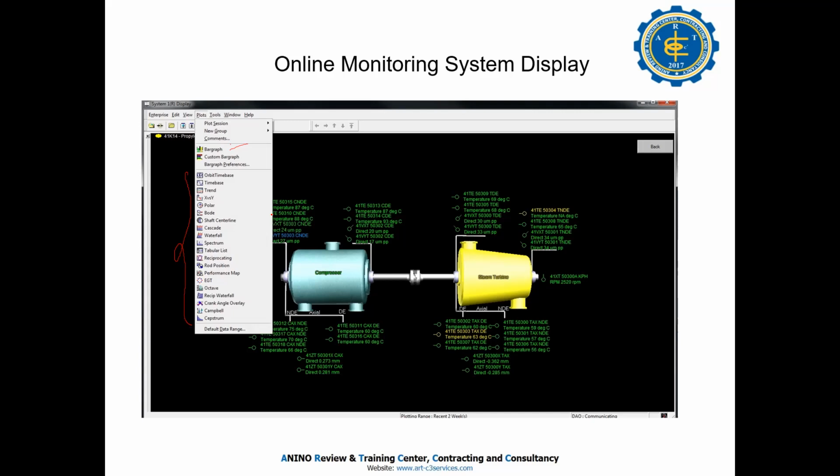That's why in my previous company, we shut down the equipment and then ran it. The first time we ran it, we had to inspect. If it was low vibration, go directly. But if it was high vibration, you can still start and run even with high vibration within the limit. Because you already ran it and then shut down, so it's not good.